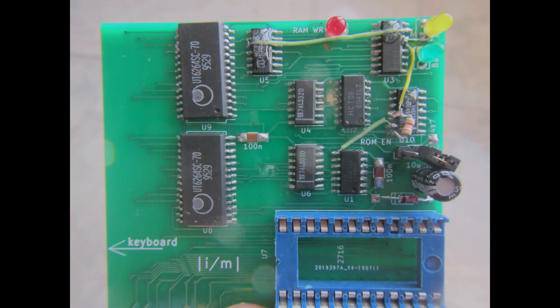So I had to make some patches to my first revision PCB, and another patch I needed was discovered when I first tried the board on my Apple II, and that was just a little design error on my part, because I forgot some golden rules of TTL design. Actually, the rule was you never pull down a TTL input with a resistor, a real TTL input.